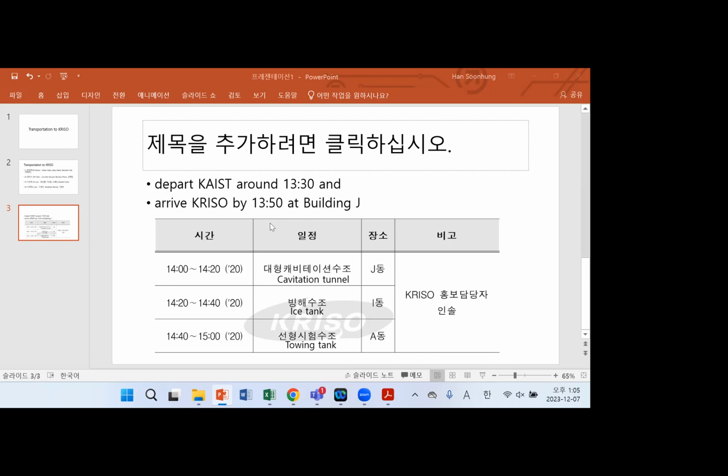So you can say this is a ship. A ship made of steel plates, and it also has its own weight. We call this the lightweight of the ship. So when it is floating, there is a small draft because of the lightweight. There is a force balance between the water and the object, the ship. So when I push down the ship, the gravity will be increased, but also the buoyancy force is returning back to my hand. That is also a balance between force and water in this case.